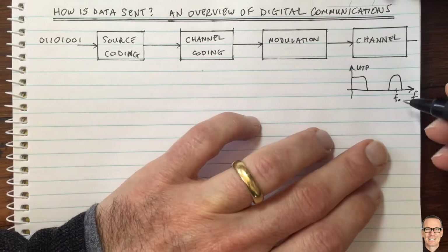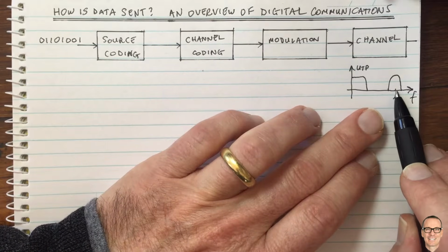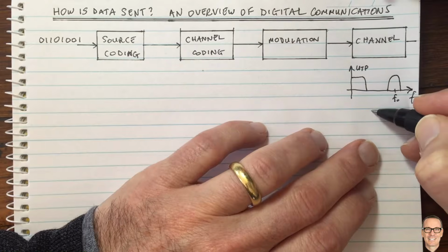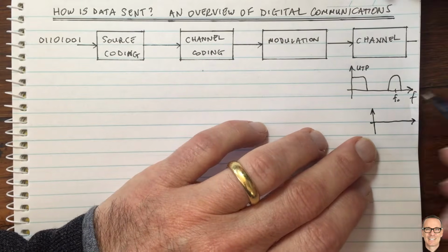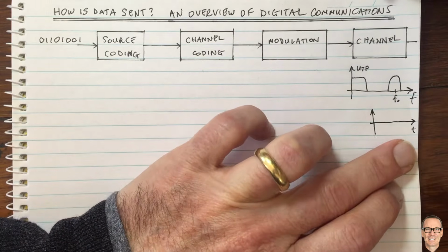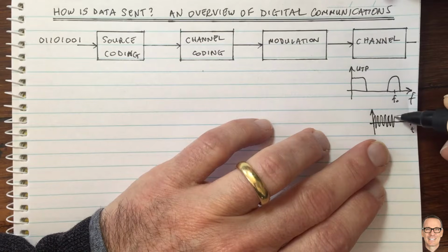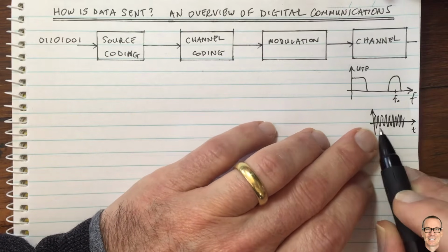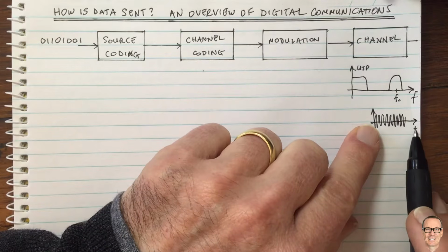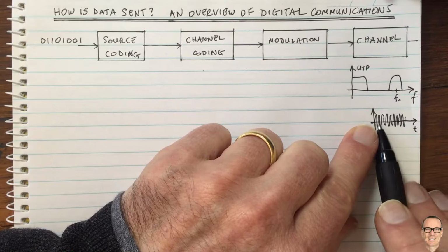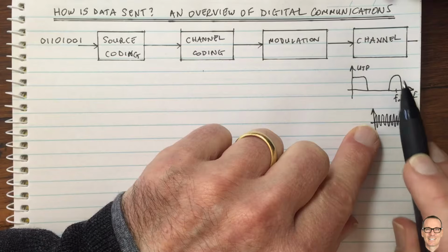Okay, let's think about what the sorts of waveforms are that exist in these channels. At this frequency here, this is in the time domain, we think of a type of signal that's a sinusoid. The signal that's exactly at the carrier frequency, if I was to think of that in the time domain and take samples of that and plot it, would look like a sine wave at that carrier frequency. So we need to transfer our ones and zeros into some sort of waveform that can be transmitted over time that looks like this, that has these kinds of oscillations at these frequencies so that it goes through that channel.